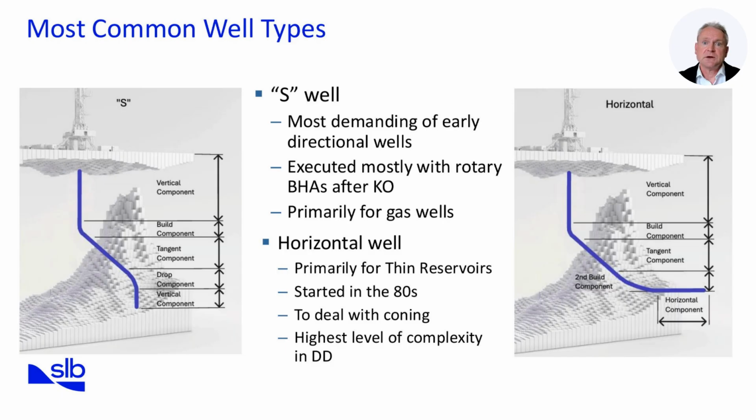Next, we have S-wells. These were the most demanding of the early directional wells. The drop sections can be challenging to achieve, mainly because dropping to vertical can also cause weight transfer, shock and vibration issues. These are common profiles when drilling gas wells.